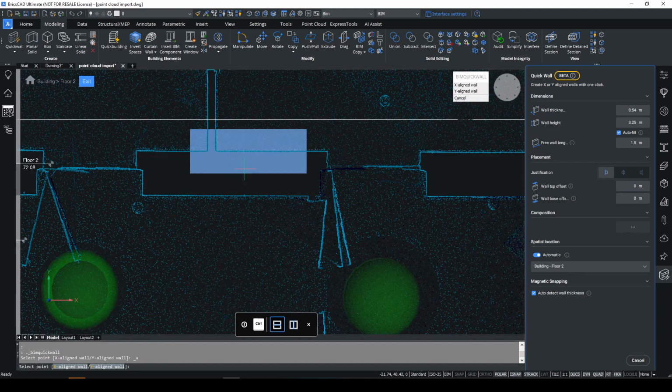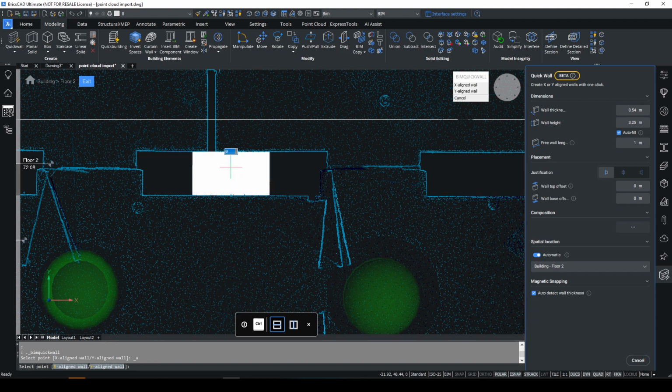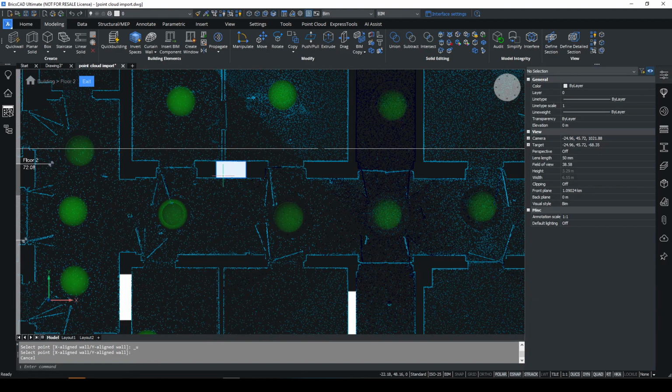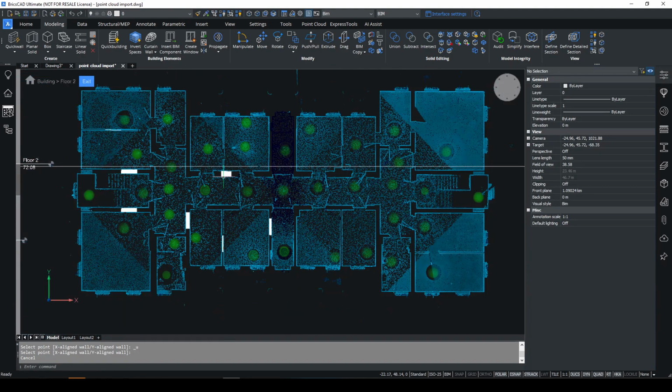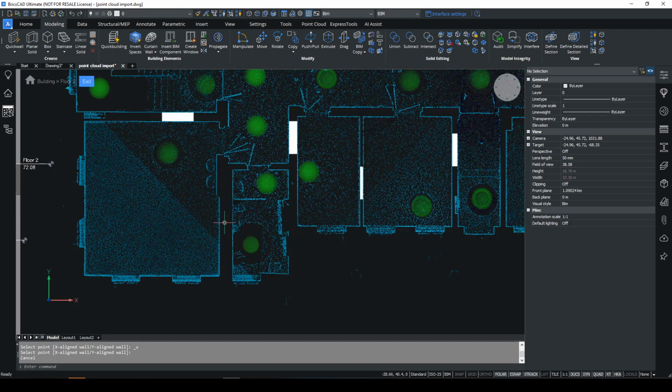The length of the segment that I'm currently doing is set to 1.5 meters. So what I can do is make that 1 meter if I want. Again, this is a personal preference where you pick the representative sample of the wall you're going to draw. So that will give us enough to get this started. We can do some more afterwards if we need. Actually, I will do one more. I'll just do a little bit of this one here.